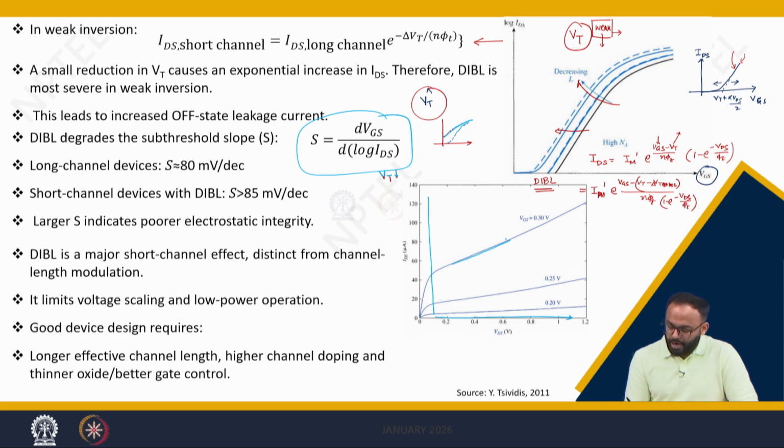We discussed that part when we were considering channel length modulation, but here, even if channel length modulation does not hold or is not occurring, DIBL allows the electric field lines to penetrate through the depletion region to the source-channel barrier and affect the current, and hence we get a finite slope in the output characteristic. Strictly speaking, in weak inversion this finite slope is much more due to DIBL.